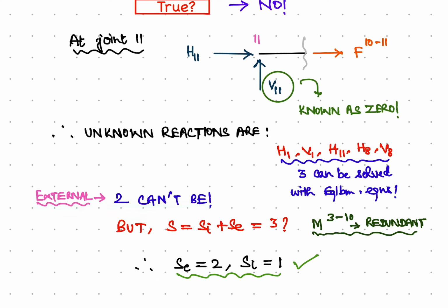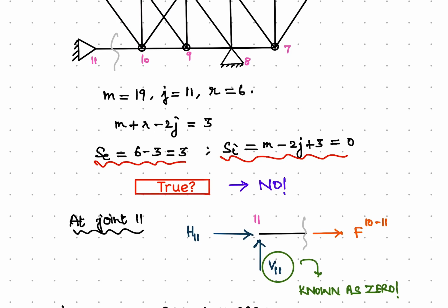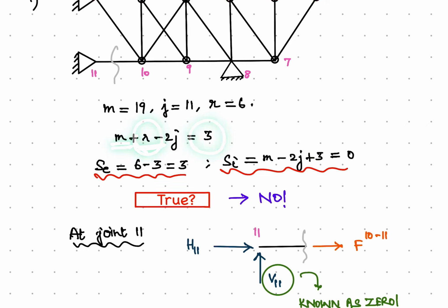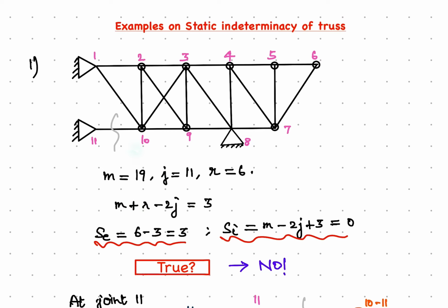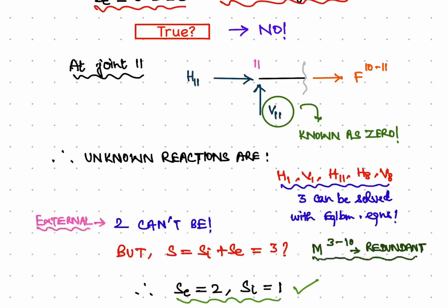All right. But we have earlier seen that the value for the overall indeterminacy, by mistake or by taking the number of reactions as 6, gave a value of 3. Moreover, I said earlier that with our basic observation, this panel is probably containing one more extra member. So we also need to check what is the internal indeterminacy in this case.